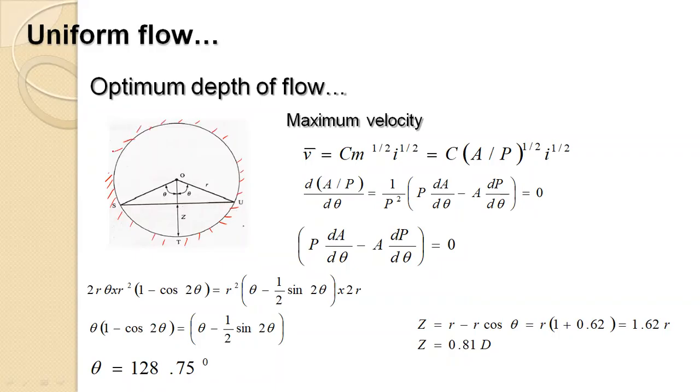So it can be a Hume pipe, right? Maybe a culvert. So there can be a flow inside a culvert. In the culvert, generally you will find partially filled flow. It's not full flow like pipe flow. There can be certain situations where the flow in a culvert is also like pipe flow when you have flood conditions. But on a general day, the flow in a culvert may be a partially filled flow.